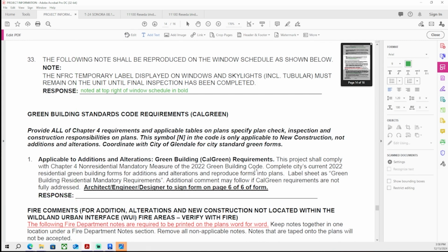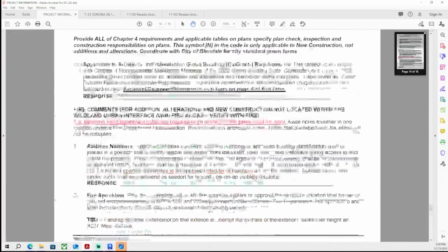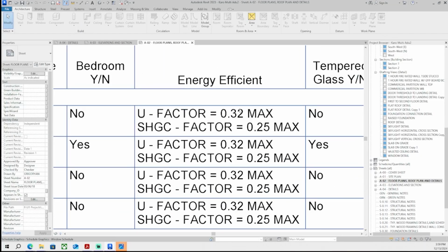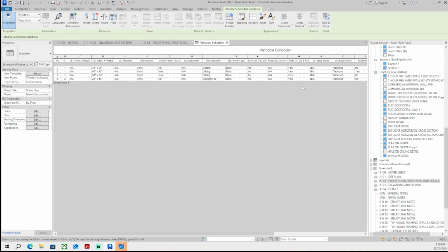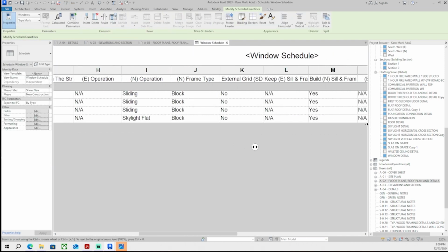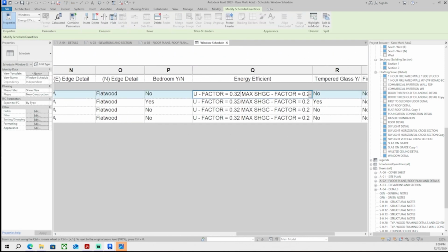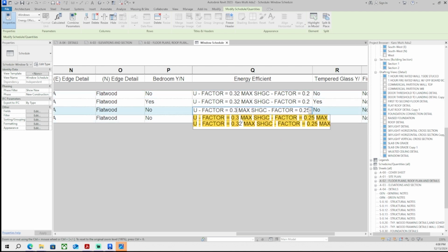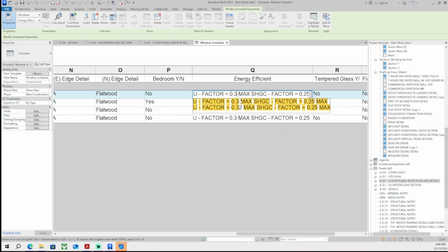The way R values work is a material has a certain R value per inch of thickness, so you thicken the material and you get greater R value. And then there's U value. The important thing to remember is that the U value has a reciprocal relationship to the R value. So greater U value means less R value. Less U value means greater R value.